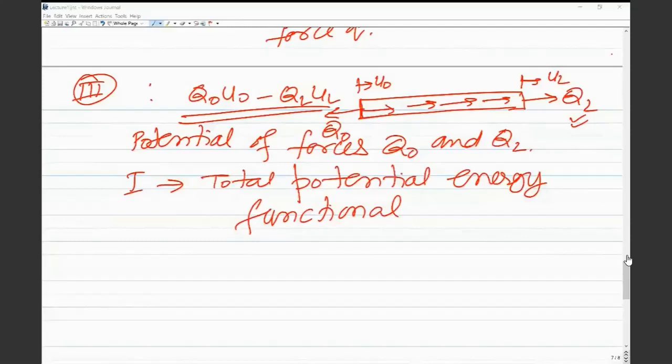Sir, we are considering, suppose, a simply supported beam. One end is a hinge. So in that hinge, V is 0 and moment is also 0. So primary and secondary, sir, can you explain? When you look at the beam problem, the primary variables are going to be deflection V and slope dV by dx. Corresponding to deflection V, the secondary variable would be shear force, which would be d by dx of EI into d2V by dx squared. So V will be specified, but the shear force would be an unknown.